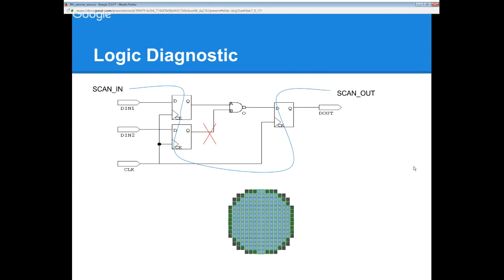I mean, if the chips make 1,000 or more, then we get many failure data. We analyze it to find where the defect point is. And then we look at whether the defect is local, not random. In that case, some part of the design has some weakness, and we can get such information from the logic diagnostic.